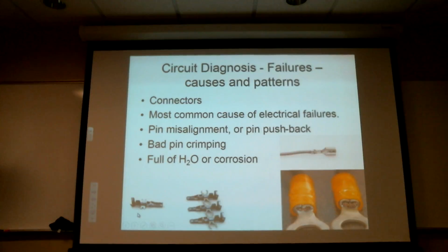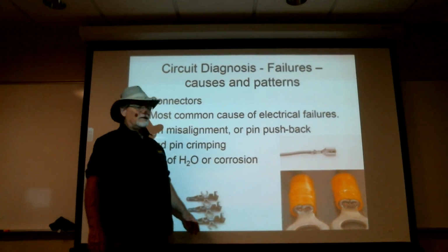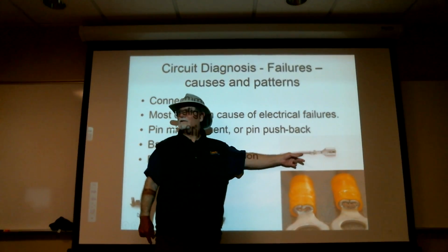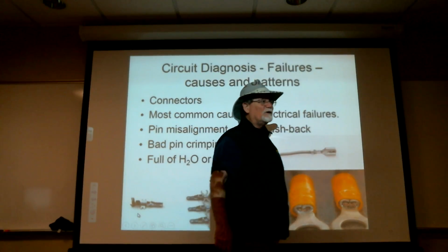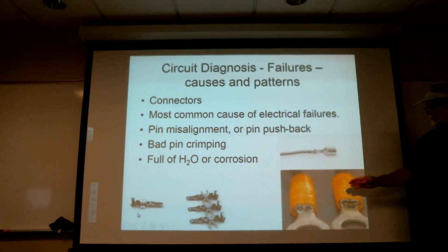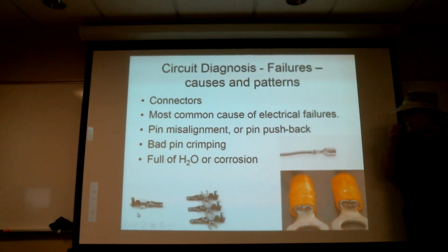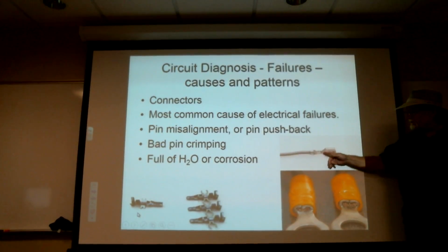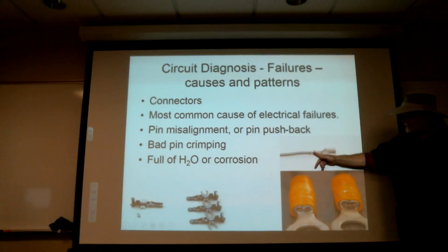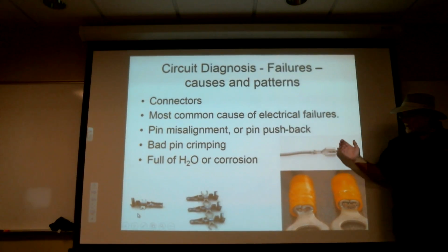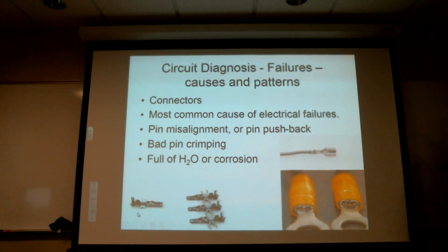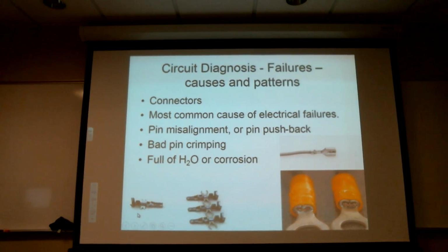The one up above, that's factory, man. That's factory. You can tell it is. It's very symmetrical, very cleanly crimped. The crimp runs the full length here. The wire doesn't extend out much. The insulation runs just underneath the insulation crimp. The insulation crimp evenly comes around and dives into the insulation and grabs it all.